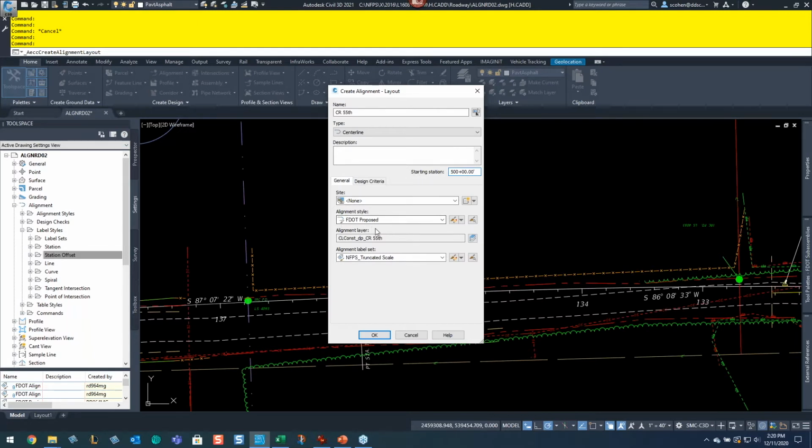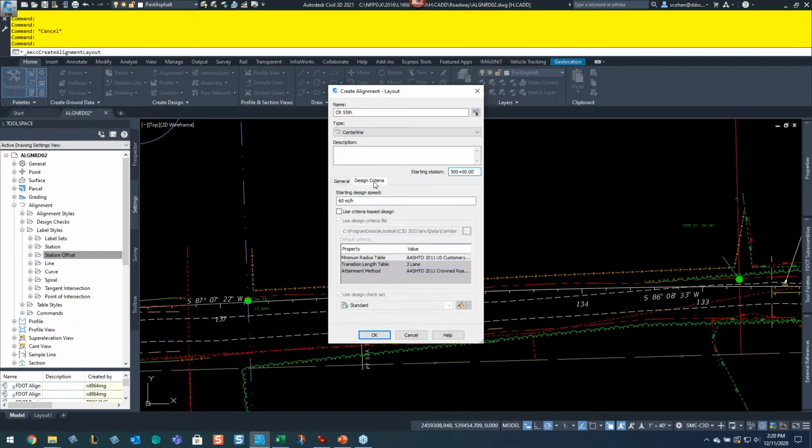And then basically we have what style. Again, there's no magic happening. This is coming from the feature settings and command settings, just everything, right? And these are the ones I want. And then this does need to have design criteria. So just an FYI, this is going to be a 45-mile-an-hour design speed. We're going to post it for 40. So I'm going to toggle this on.